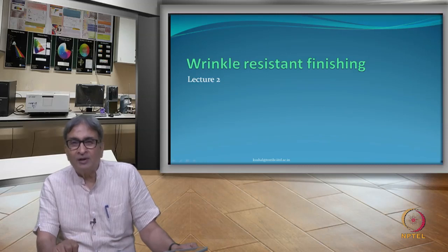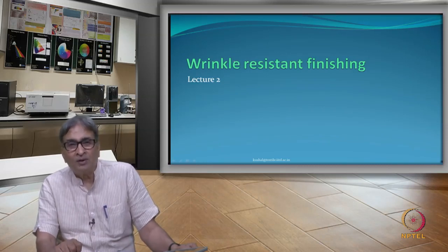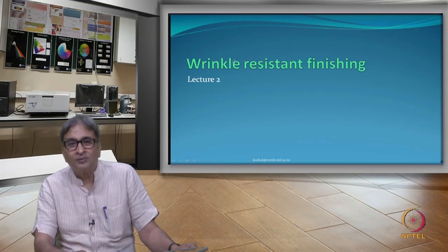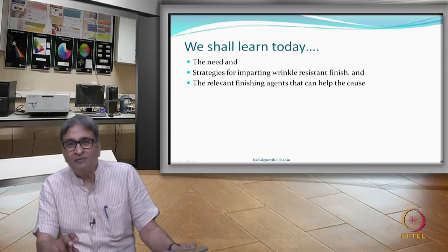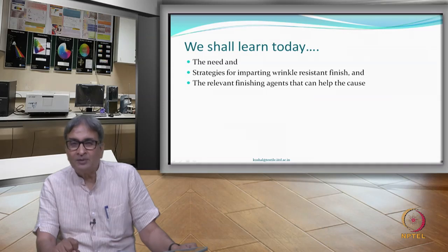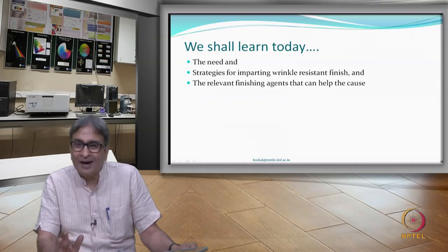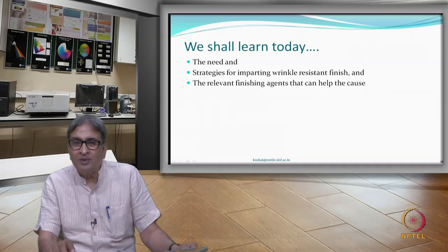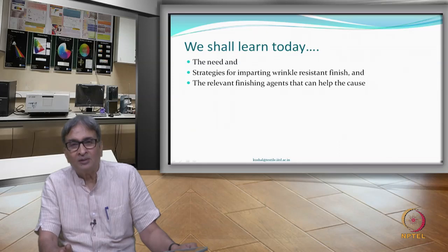So, today we will concentrate a little more on wrinkle resistant finishes and learn a few things about it. We will first understand the need, why it happens and why we should do it. Other is, do we have some strategies to impart wrinkle resistance finishes and what are those strategies? And some relevant finishing agents that can help this cause will also be discussed today.